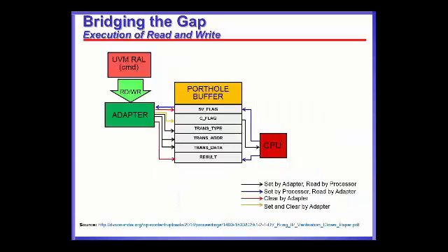Okay. Now let's look at the kind of protocol that we defined to achieve hardware to software communication, and it's pretty simple. The idea is that any processor would need a transaction type, whether it's read or write, a transaction address, to which address you want to read or write, and then the data that you would like to write.